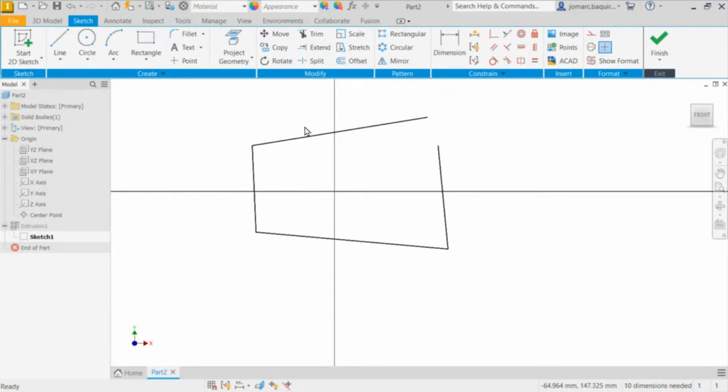So the difference between Inventor and SolidWorks, there's a consistent pressing of F8 and F9 for you to not accidentally select the constraint itself. Okay? So next, I want this top line to be perfectly horizontal.